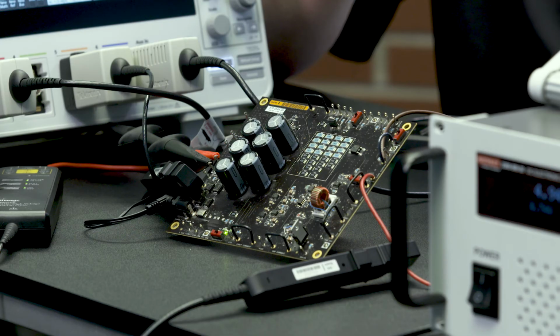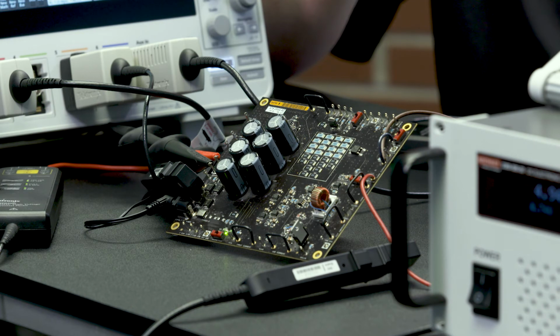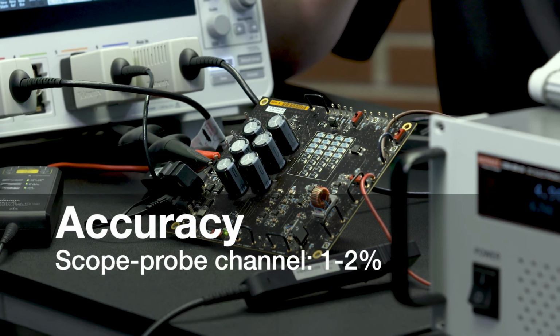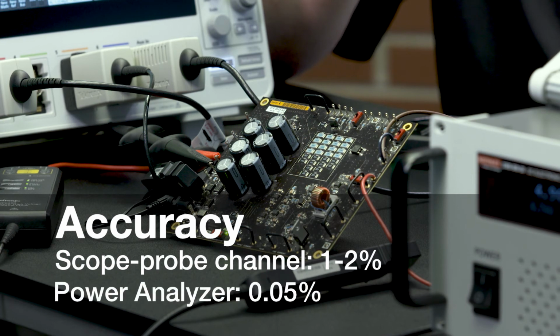The power software on our scope emulates the measurements of a traditional power analyzer, but makes it more convenient as a choice in the design or debug phase. Scopes and probes are great for convenience, but a scope probe channel is usually close to 1 to 2% spec accuracy, as compared to a 0.05% accuracy on a traditional power analyzer.